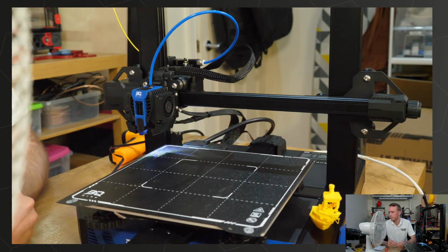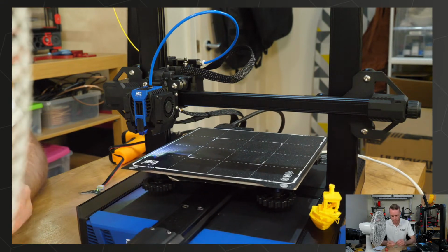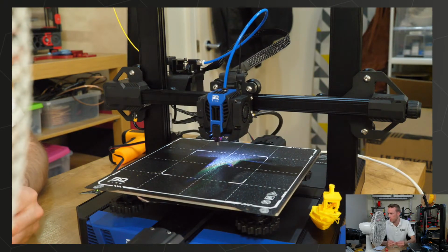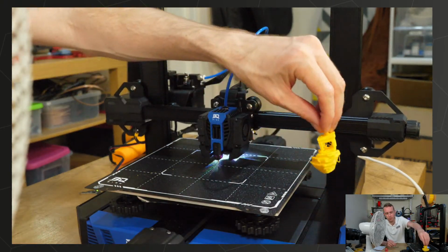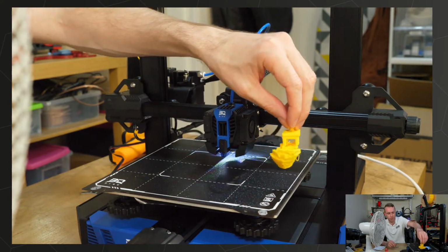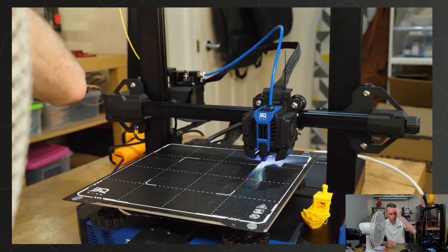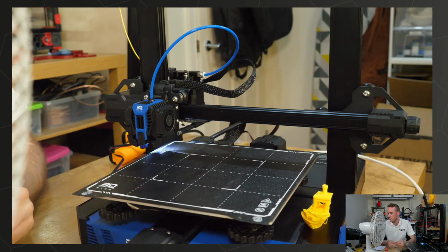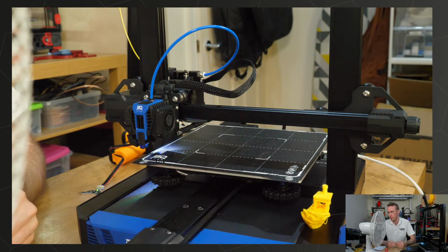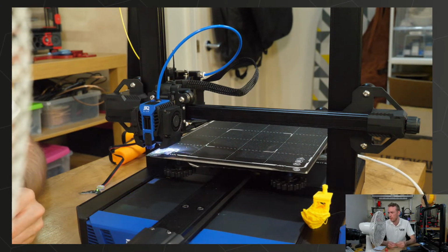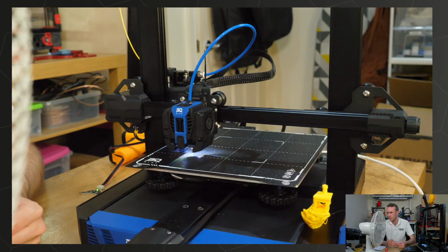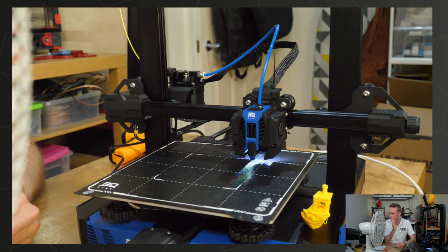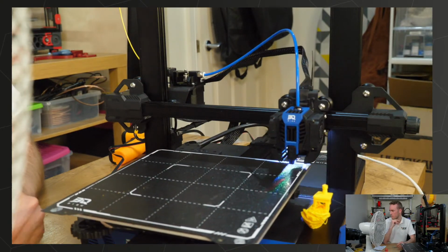You could put a linear rail, but I don't think it's really necessary. This is a great test as a demo of maximum performance, but it's not necessarily something you're going to be printing at all the time. This bench sheet, I didn't actually print with 80K acceleration. I did go pretty high, but not 80K. In the middle of a print, you don't want any risk of something like that happening, so you print a lot slower than this. There's not much speed advantage, I don't think, realistically, between like 15, 20k and 80, because you're getting to your maximum speed so quickly that the time you save is minimal.